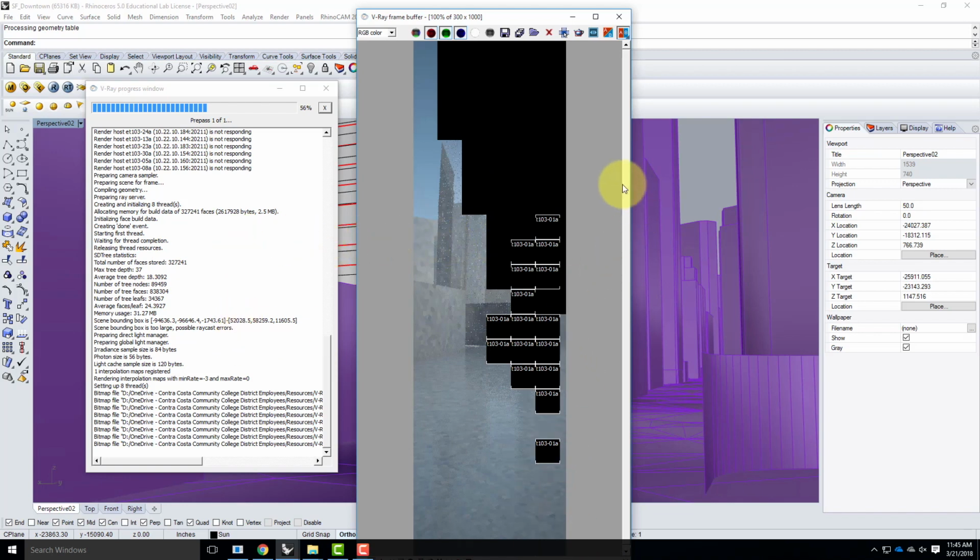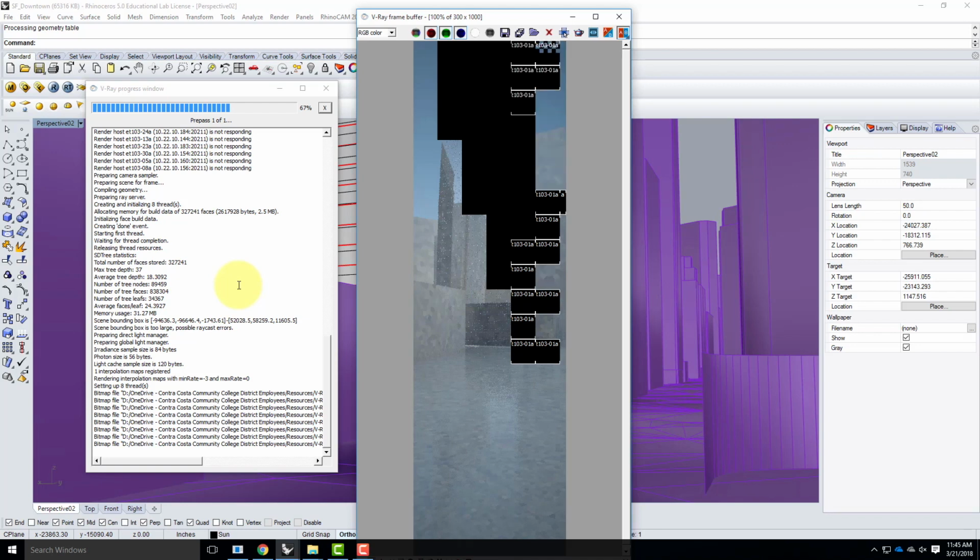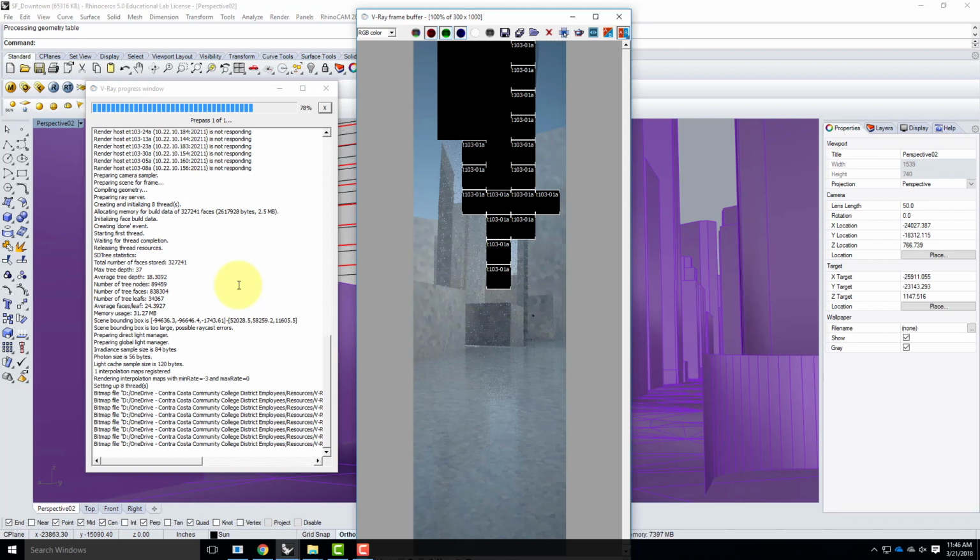So I'm not getting the benefit of any of the other computers yet. At some point during this rendering, I may pick up other computers. It takes a while for the files needed to render to go out to the other computers, load those files, and then start spitting stuff back. So don't expect it to pick up real fast. Where this is useful is not in the 2 to 3 minute rendering. It's in the 30, 50, hour-long renderings where you're borrowing stuff. Okay? It is not uncommon when you get to your final renderings to have renderings that last an hour or 2.